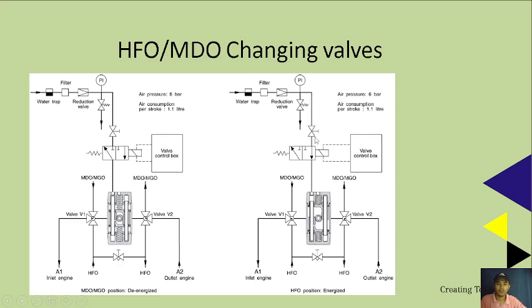Then we have a control main valve here, and then a 3-2-way valve, solenoid operated with spring return, controlled via the valve control box. So this can be operated electrically on automation via PLC maybe. You can also do that. And then here's the valve which will do the changeover. You can also do the manual way of changing over the fuel, or if you don't have this mechanism.